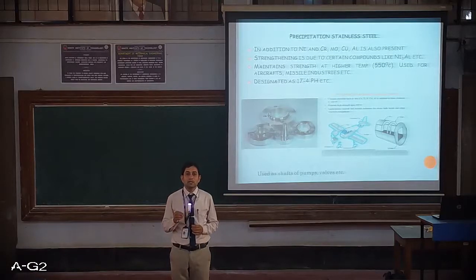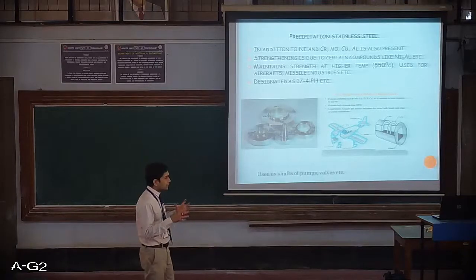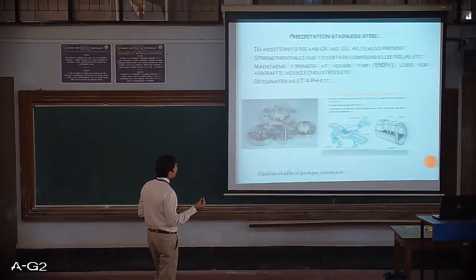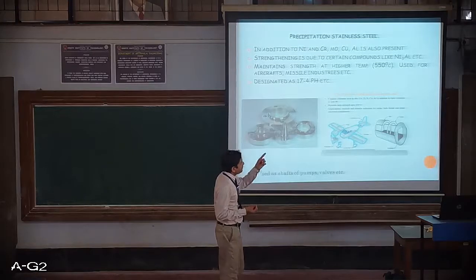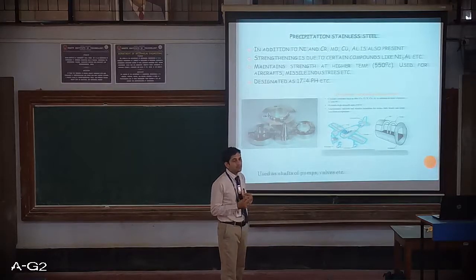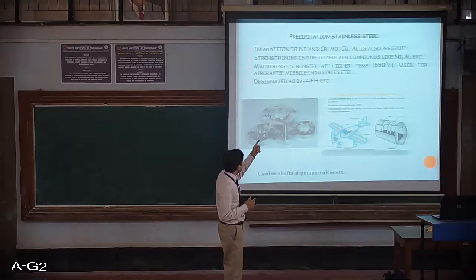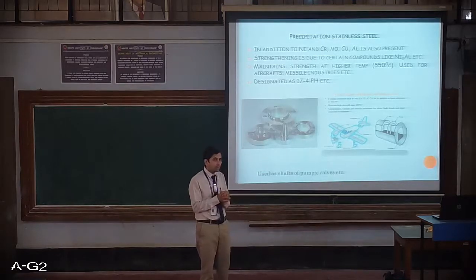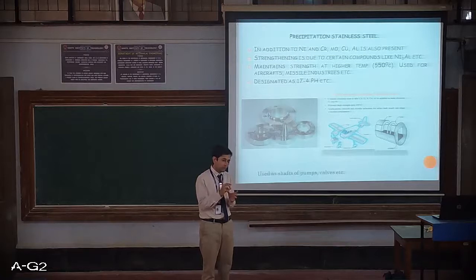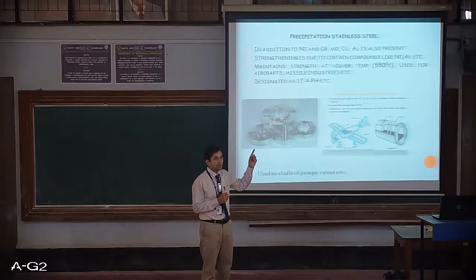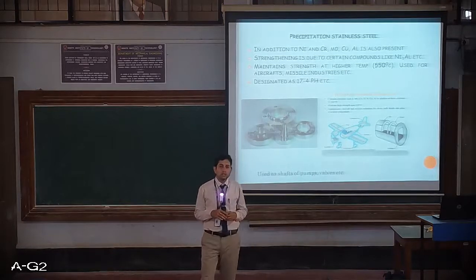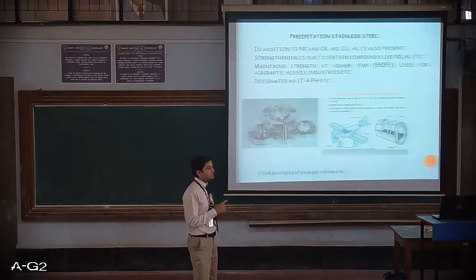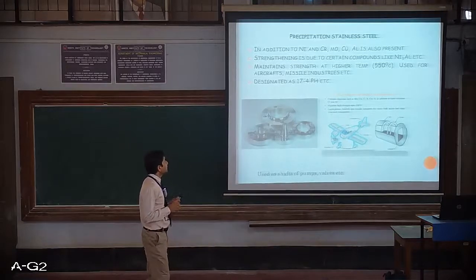because here what happens is that it forms a kind of precipitate or some kind of compound like nickel aluminum, and settles inside the metal component. Like that, I have said that the nickel and aluminum which you have added to the stainless steel both will combine and precipitate, or form a compound, that is nickel aluminum, Ni3Al, and that will give specific properties to that stainless steel, right? So that is called precipitation stainless steel, and it maintains its properties at high temperature.